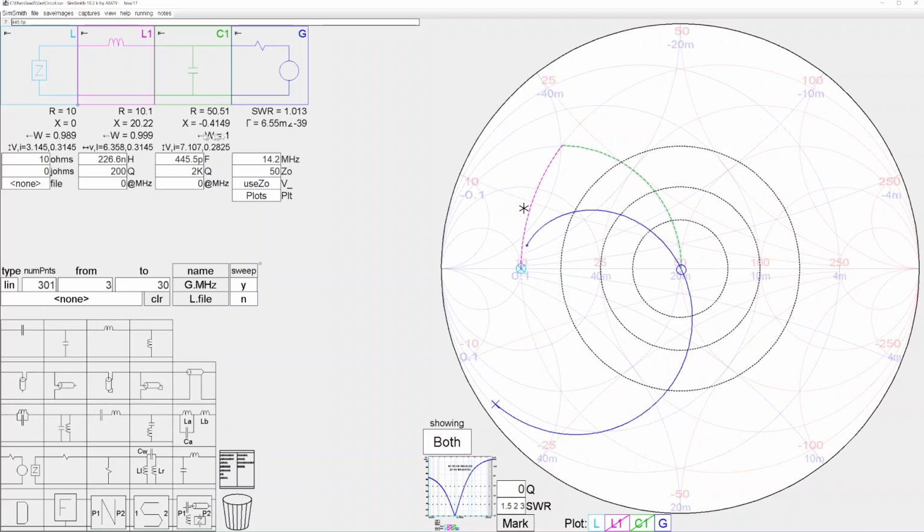The next thing I want you to observe is the power. I'm injecting 1 watt from my generator into this first component. It's injecting 99.9% of that into the next component, pretty efficient. And what's going into my load is 98.9%, pretty darn efficient. Of course, I've got a very simple case here, but you can see that we're solving this.